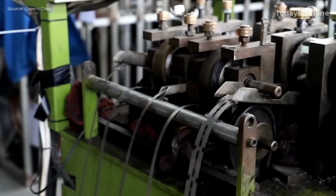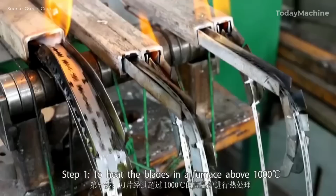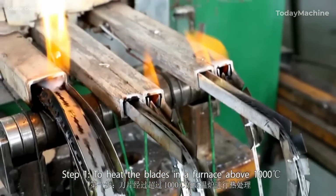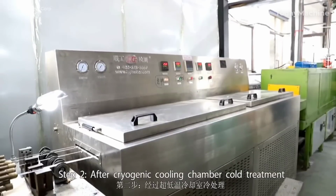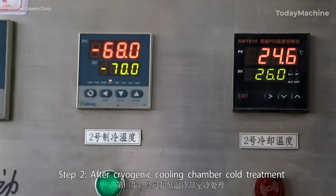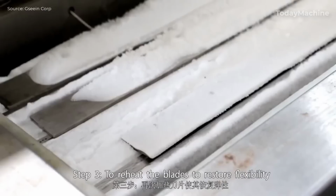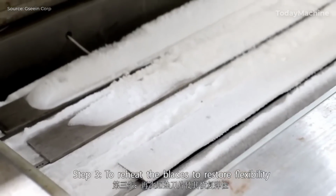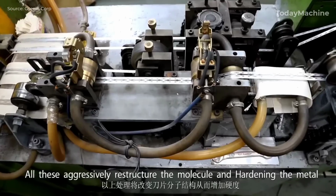The second step involves cryogenic cooling, where the blades are rapidly cooled to sub-zero temperatures. This step further enhances the metal's hardness and durability. The third step is reheating the blades to restore their flexibility, ensuring they are not too brittle. These thermal processes collectively harden the metal and give it the necessary strength and flexibility for cutting.